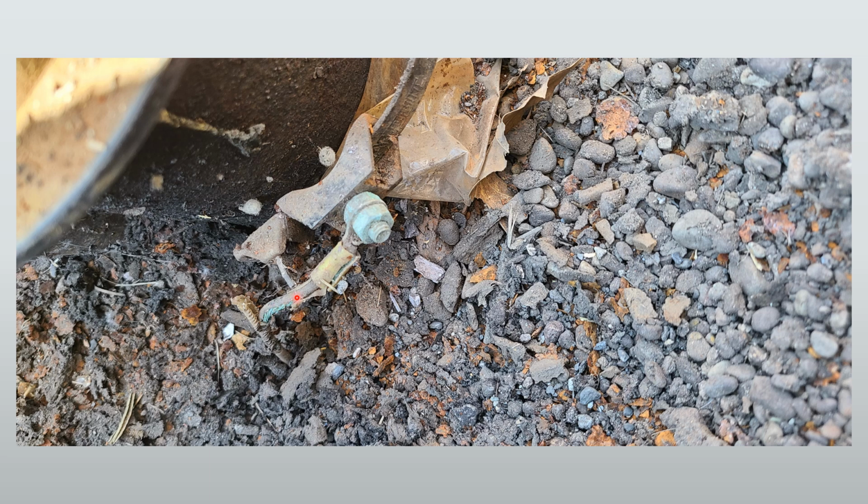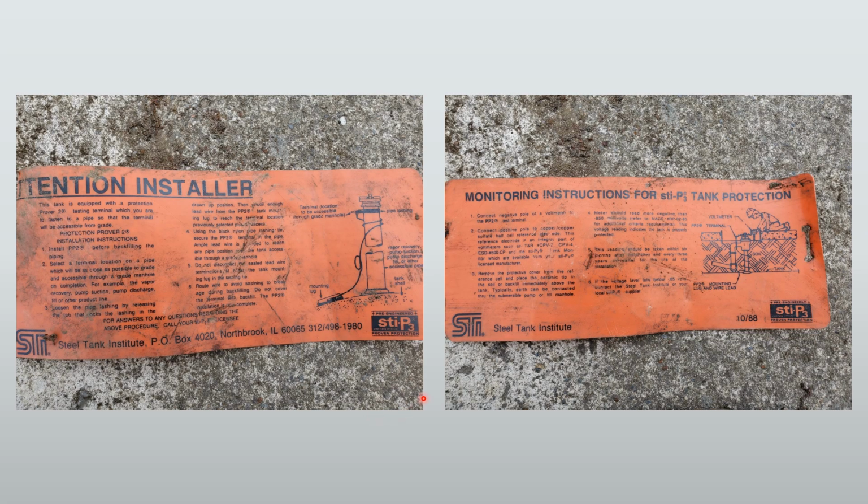So this is the enlarged structure of our Type 3 test lead. You can see that the coating on this one's a little bit damaged coming out. So this is the structure part of the tank. This will actually receive protective current from the anodes since it is exposed. So that's not too much of an issue as long as we don't lose continuity with the tank structure. We can verify continuity by testing the tank bottoms unless the tank is lined, and then we cannot get access to the tank, and it becomes very difficult to determine continuity with the tank structure if these test leads are damaged.